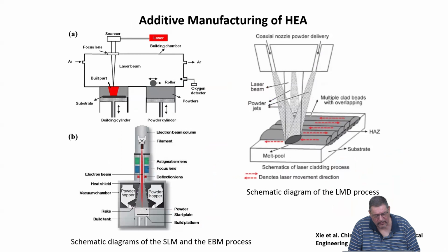Additive manufacturing is very hip these days, and everybody investigates it. It is basically similar to laser cladding, right? I mean, you can not only use lasers, you can use all kinds of energy sources in order to do the additive manufacturing. I think most people using high entropy materials use these laser-based processes, powder bed fusion.